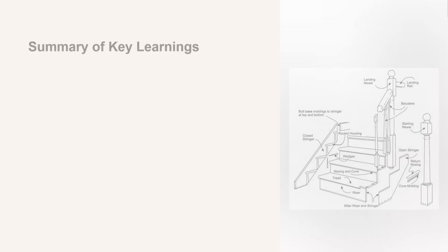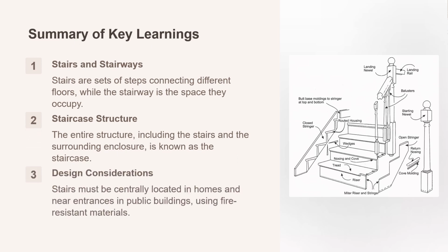To summarize, what we have learned till now is stairs are sets of steps connecting different floors, with the stairway being the space they occupy and the staircase referring to the entire structure. Key considerations include locating stairs centrally in homes, near the entrance in public buildings, and using fire resistant materials to ensure safety.